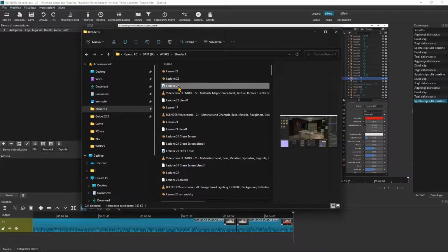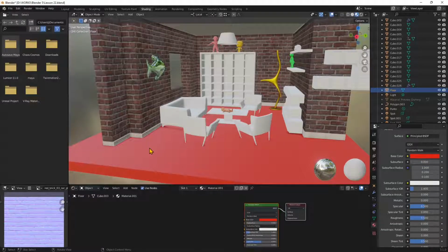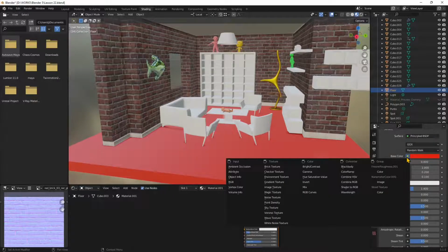And we see an example here. Let me show you right away. This is using the actual HDRI. So also in the materials, if we apply textures, they're going to boost the realism and physical accuracy of our material. To do that, we can simply click on this yellow dot next to the base color, and this lets you apply textures.